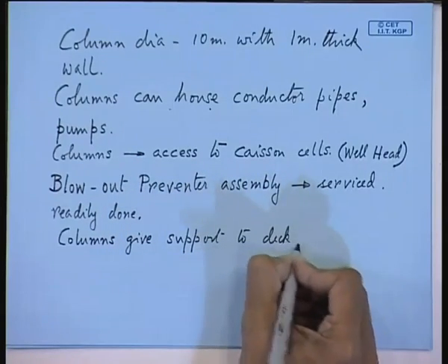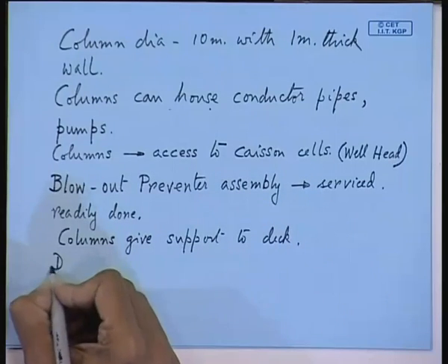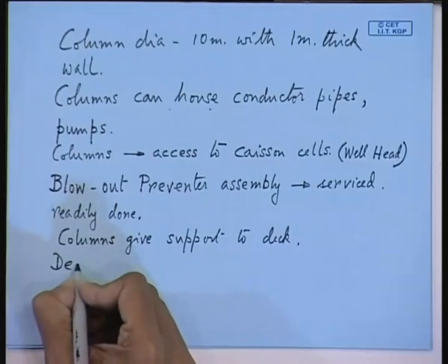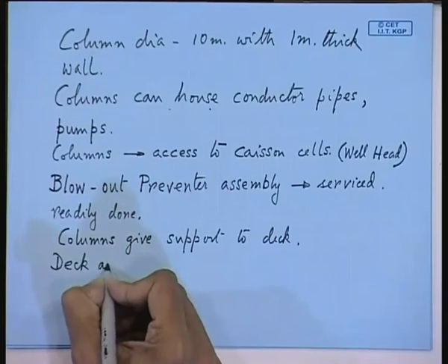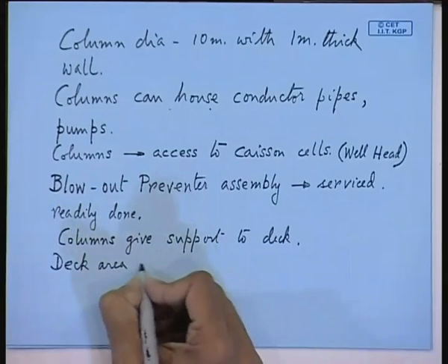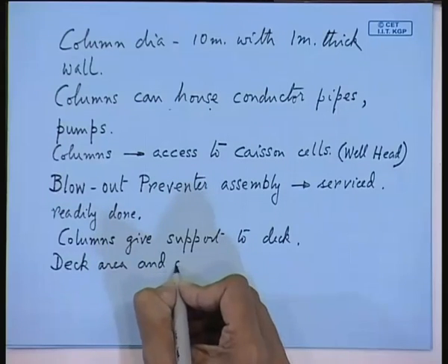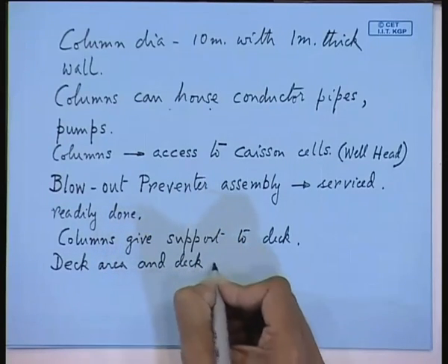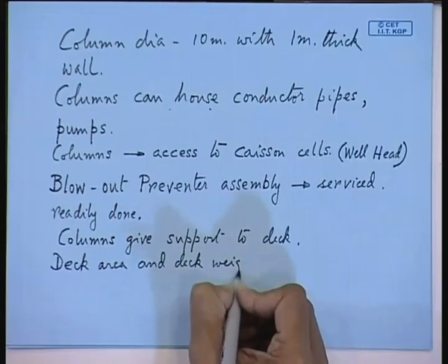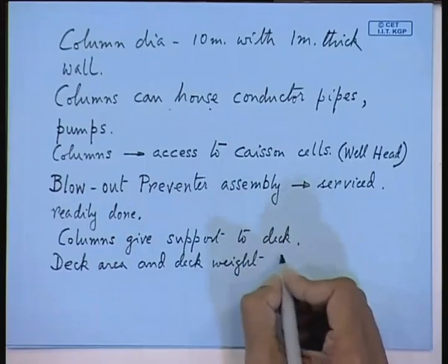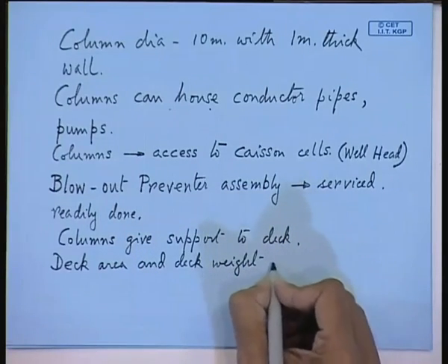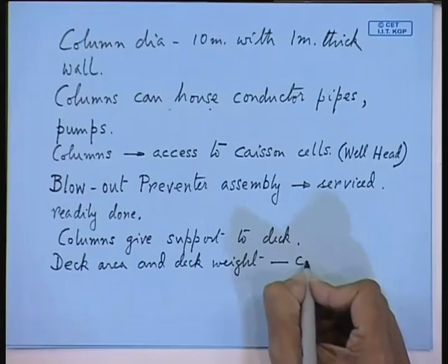And the deck area actually determines column spacing. Deck area and deck weight are the two governing factors you use to decide column size and spacing.